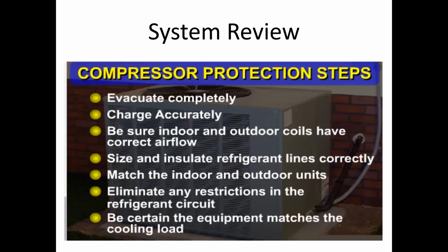Yeah, we all know this. Your systems have to be properly matched, right? Indoor and outdoor, you have to have a matched system. So as we're talking about this holistically, the whole system, you've got to evacuate, pull vacuum down to 500 microns. You've got to charge accurately.